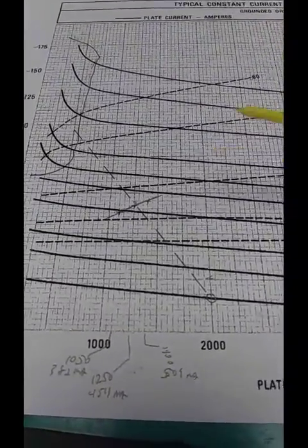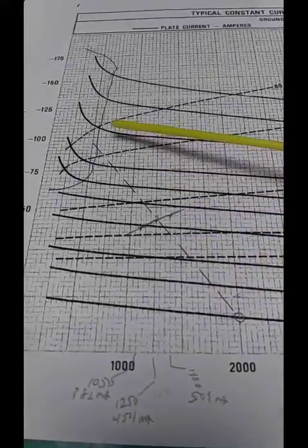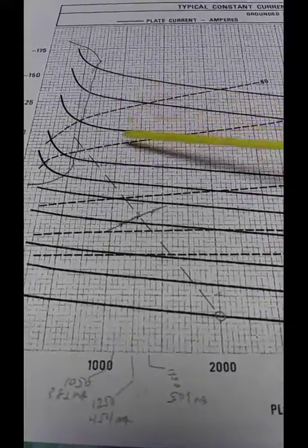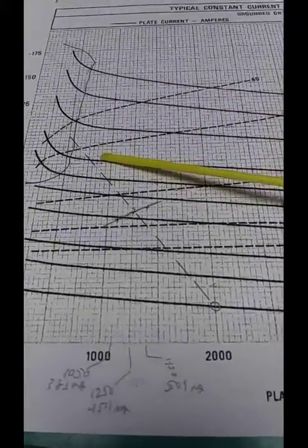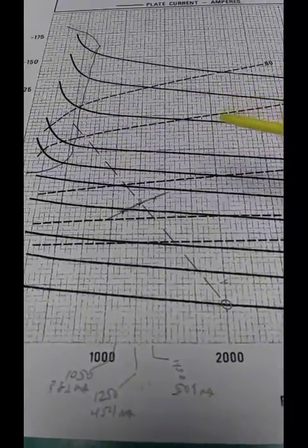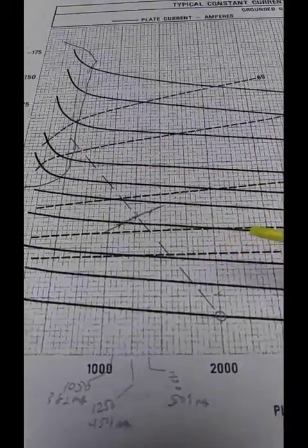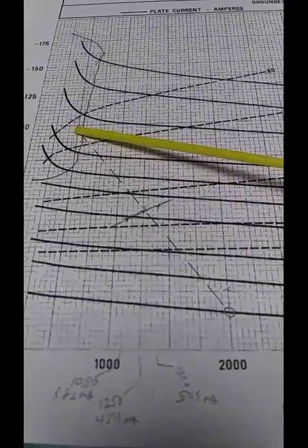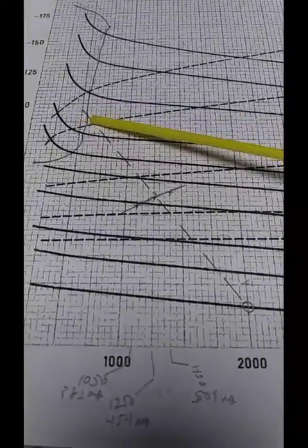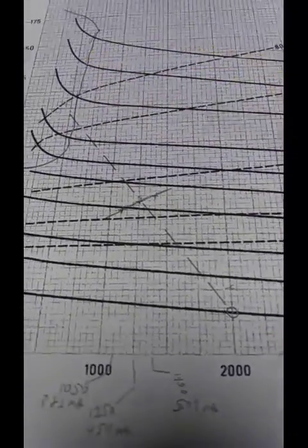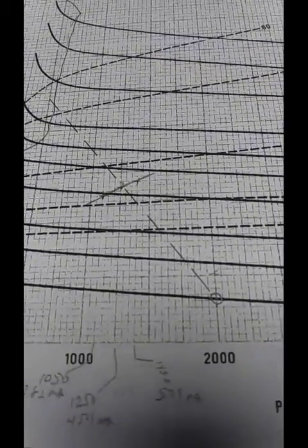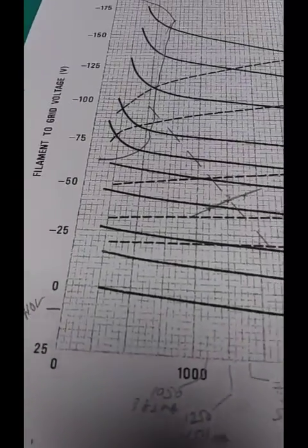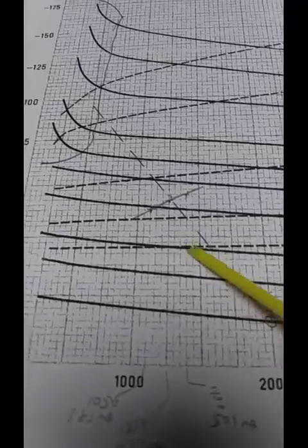And so I pencil in that line with pencil, because I drew this distortion area, and with pen it's not accurate and I can't erase it. But it's cheap and easy to print these out. But there's a load line, no guessing at the maximum plate current. And this is probably going to be underdriven enough and low enough power that no matter where this is in this ballpark, it's not going to overdrive the tube. We sure don't want it to be up here. But this starts at the 0 drive plus 10 volt grid voltage at 0 plate current.